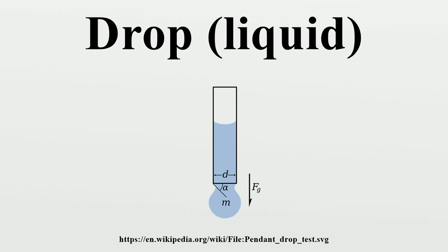Drop adhesion to a solid. The drop adhesion to a solid can be divided into two categories: lateral adhesion and normal adhesion. Lateral adhesion resembles friction and refers to the force required to slide a drop on the surface, namely the force to detach the drop from its position on the surface only to translate it to another position on the surface. Normal adhesion is the adhesion required to detach a drop from the surface in the normal direction, namely the force to cause the drop to fly off from the surface.